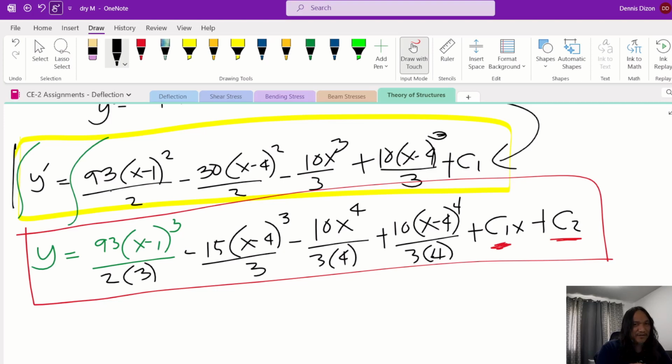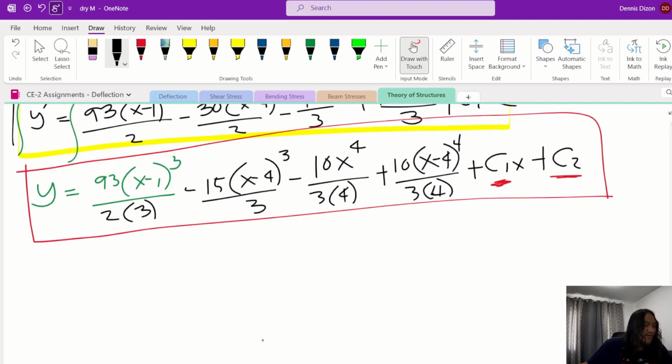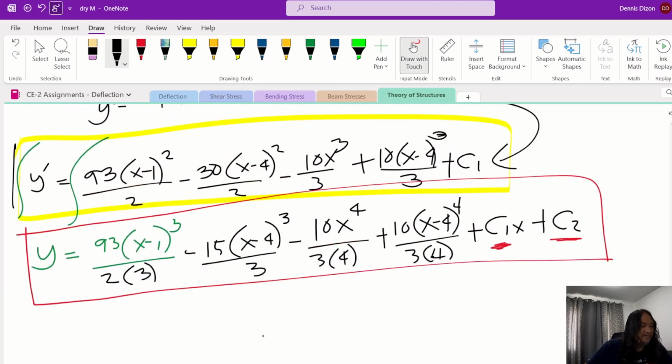It will not be exactly 0, right? It will be really close. Since this is in millimeter or in meter, and deflection is usually calculated in millimeter, you can set your distance increment at, say, 0.001, your assumption. So it will take time to do trial and error, but that's the easiest solution if it yields a cubic equation.